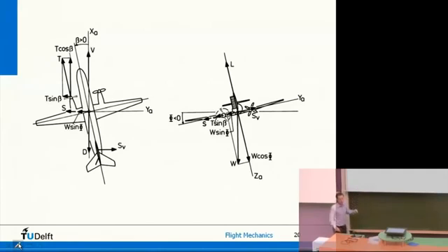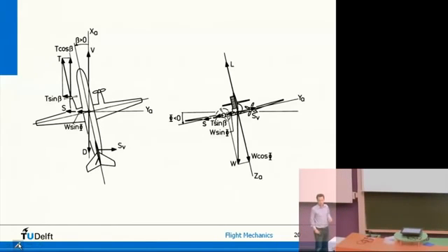That will be the case, for example, if you have an engine failure. If one of the engines fails, then the other one has to provide all the propulsive force. So that means you get a moment around the aircraft center, and the aircraft nose will want to go to the left or the right. And you have to compensate for that with a rudder input. But clearly, even though you can fly with an engine failure, it's not something you would call symmetric.